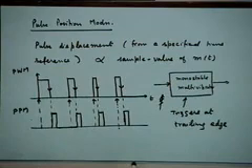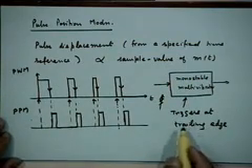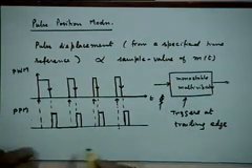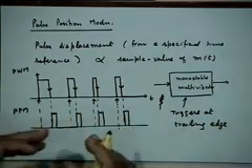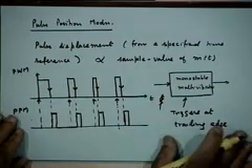Okay. So that is a PPM signal. That's how you can generate a PPM signal. So for the demodulation, once again one has to go into the spectrum. I think you won't like me to write another expression of that kind. But without writing the complete expression, I will just write the first two terms of the expression, which are useful to understand what the nature of the demodulator would be. Actually PPM and PWM bear the same relationship to each other that FM and PM bear to each other.